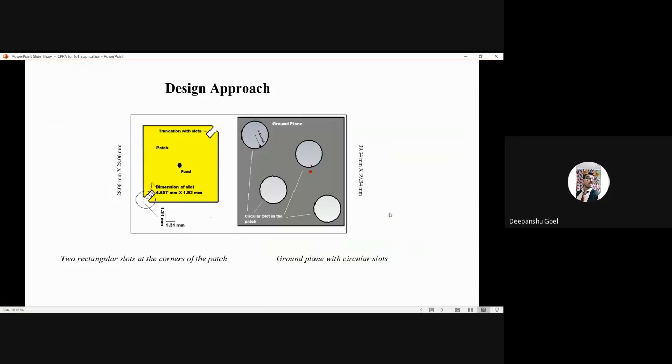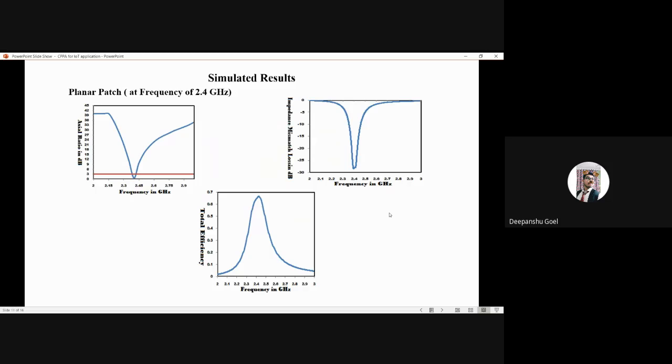Design. So I'm going to present the antenna design to gather your insights. We have truncated the patch at the corners and added circular slots at the diagonals in our ground plane. You can see we considered many sizes, shapes, and positions of our truncated slots with iterations in the CST device. Now I'll show you my simulated results.